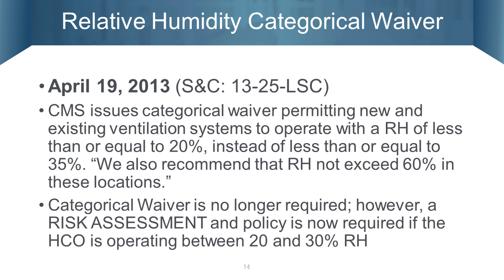And one I can think of in particular is medical equipment as an ESU unit that was designed for flammable anesthetics. The manufacturer strictly says they're not allowed below 30% relative humidity. So it's required that you go through a risk assessment process to document that you, in fact, feel it's safe to lower your bottom range down to 20%.